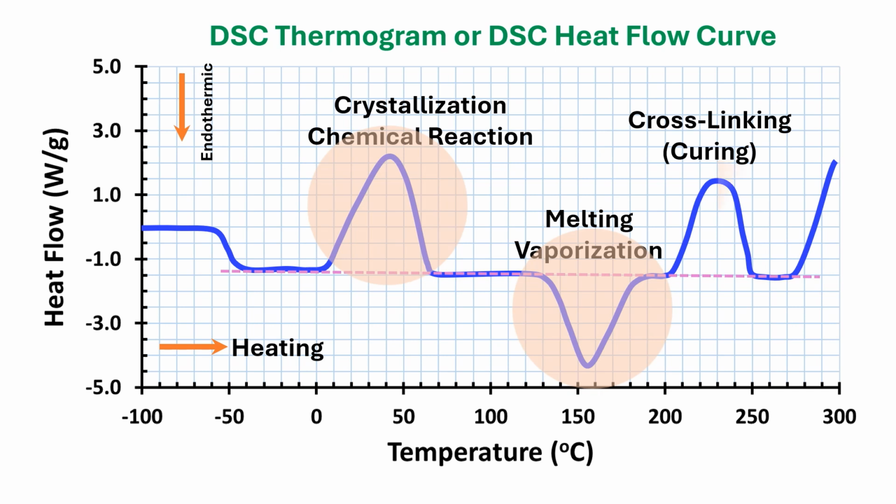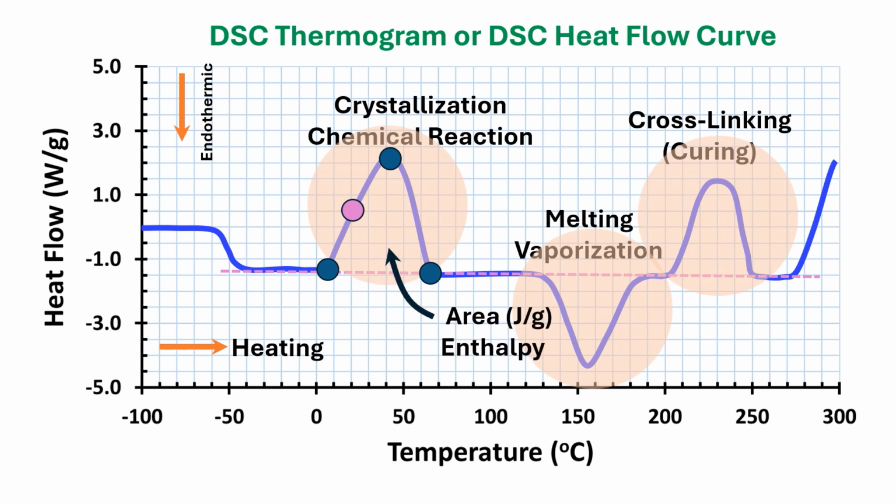An example of the third, exothermic peak, is cross-linking, that is curing. This could be a structure building in the sample. Most commonly, onset, peak, and end temperature are recorded to characterize the process. However, in some instances, maximum slope is recorded. Area under the peak is considered as the enthalpy in this process, that is joules per gram.